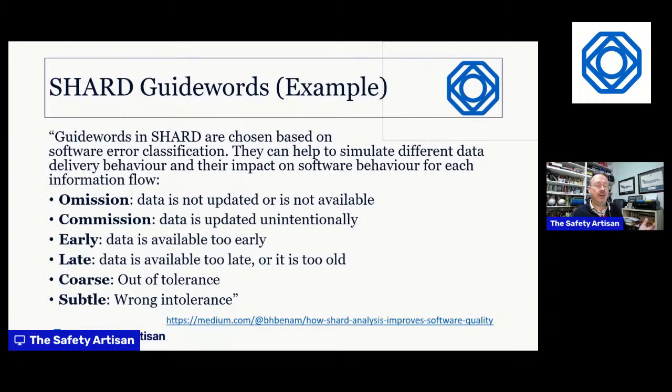This is where maybe a quick functional failure analysis will inform you. Understand the way different digital devices can fail, or the way the software can fail, and then you'll have a much sharper analysis. But it's still very, very similar to HAZOP. Even if you start off with guide words or deviation words that are not perfect, if you do a coarse one or a dry run, you'll improve them for your system.